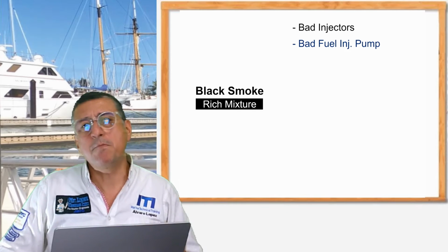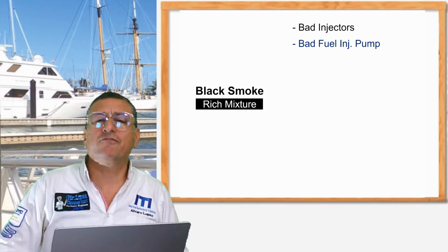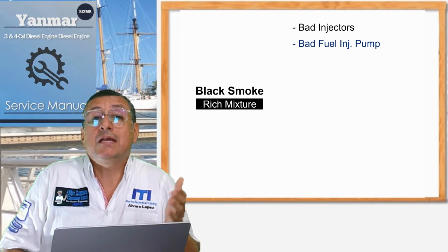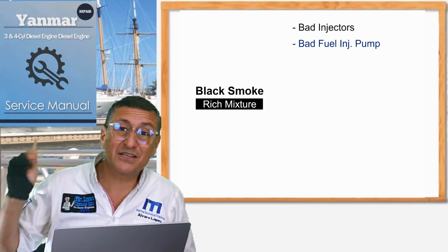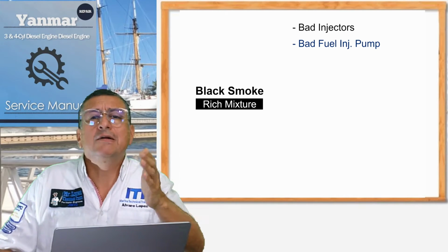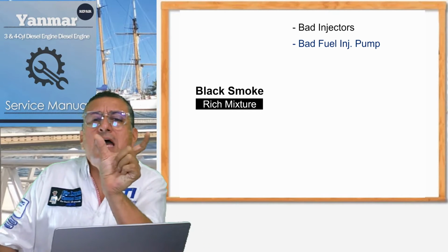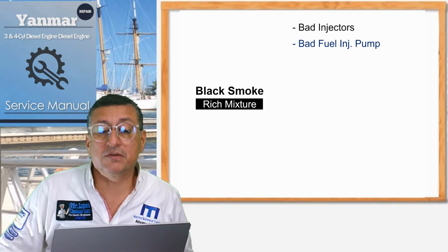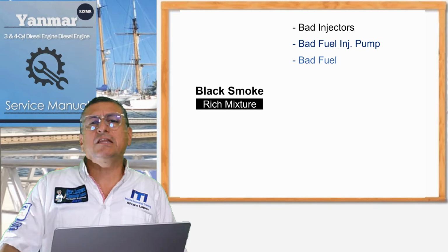For that reason, my friend, both of them, injectors and fuel injection pump, should be calibrated periodically according to the intervals recommended in the service manual. This is very, very important. Each manufacturer has different time windows for those services. Follow the service manual.